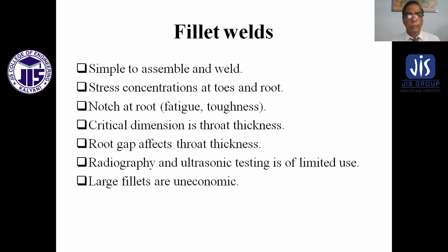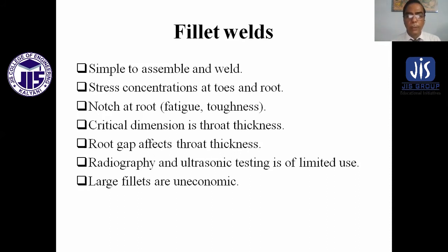Fillet weld. Simple to assemble and weld, stress concentration at toes and roots, notch at root, fatigue and toughness. Critical dimension is throat thickness. Root gap affects throat thickness. Radiography and ultrasonic testing is of limited use. Large fillets are uneconomic.